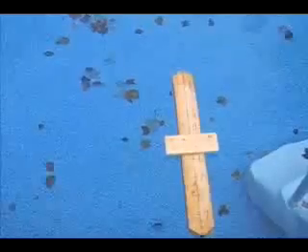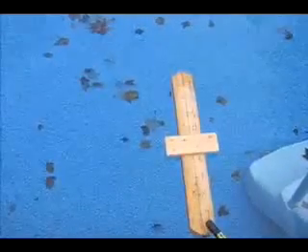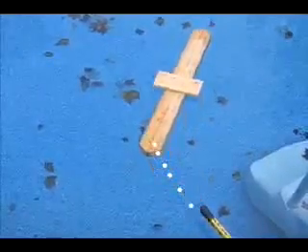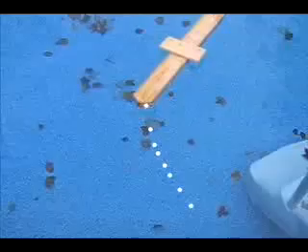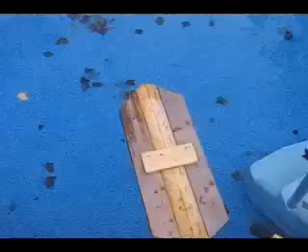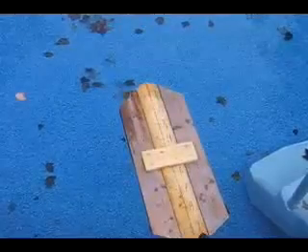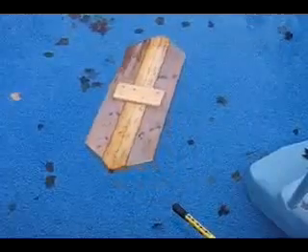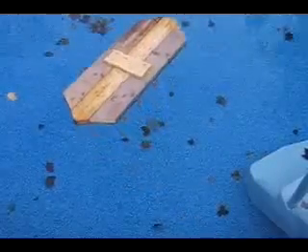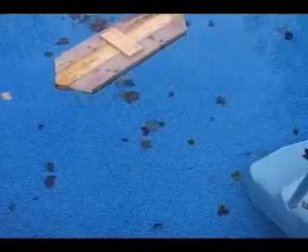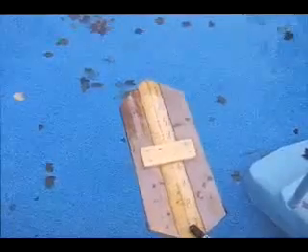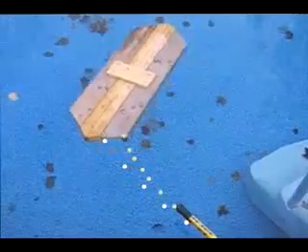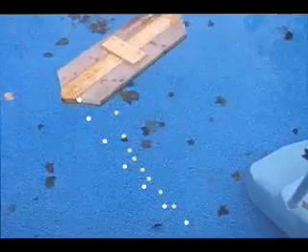Let's compare two ships with the same length, same draft, the first having only a third of the beam of the second one. After the ships have developed sideways motion, it is harder to stop the drift of the wider ship, 3 times heavier, for approximately the same lateral resisting force. That resisting force being here the surface area of the wall of water, which is represented by the ship's length times the draft.